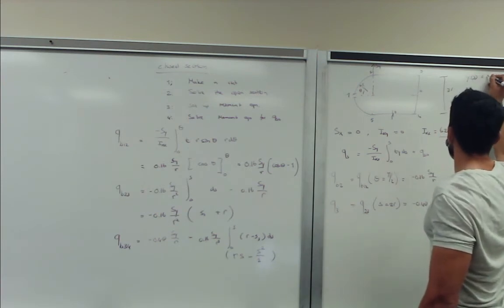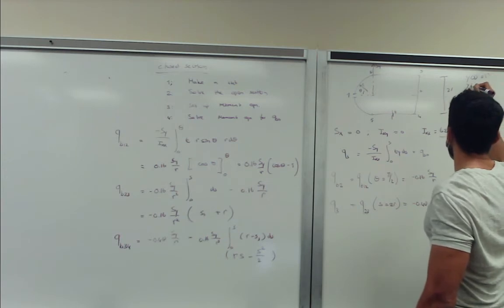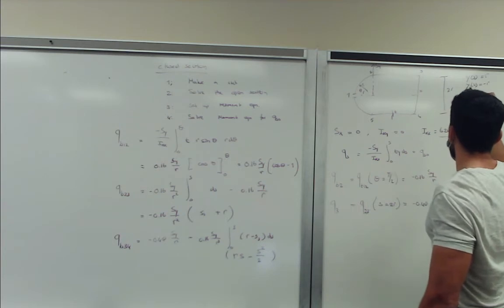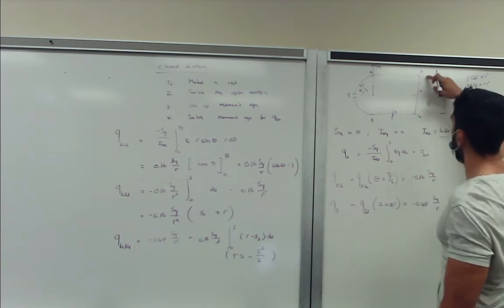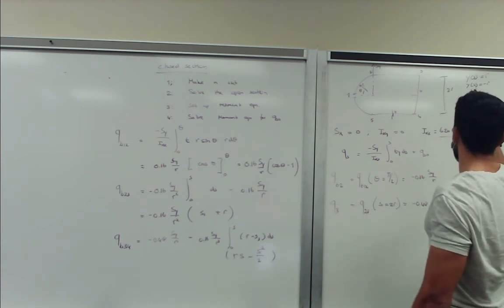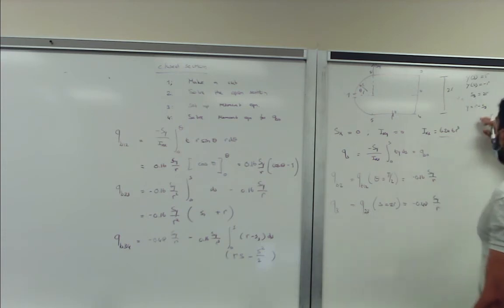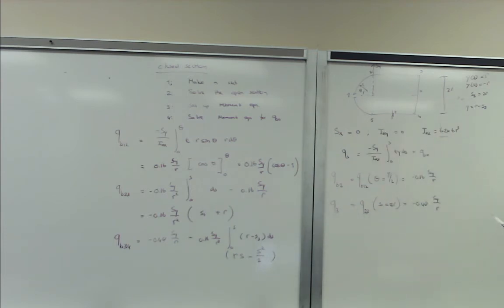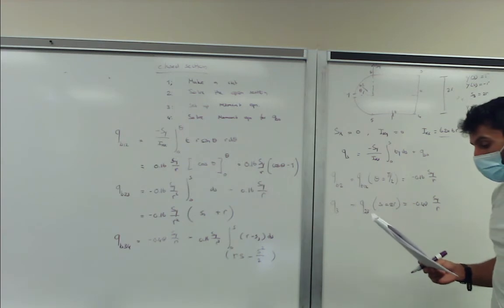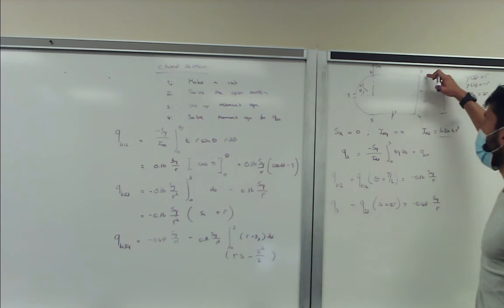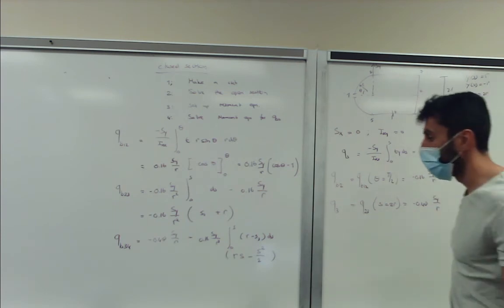y at point 3 is equal to r, y at point 4 is equal to negative r, and the s that we travel from 3 to 4 is a total of 2r. So our y equation becomes r minus s3. And if you evaluate that, all those conditions are met. Okay. And of course, we can evaluate at point 4. And based on symmetry, we could also immediately say this is the same as point 3.